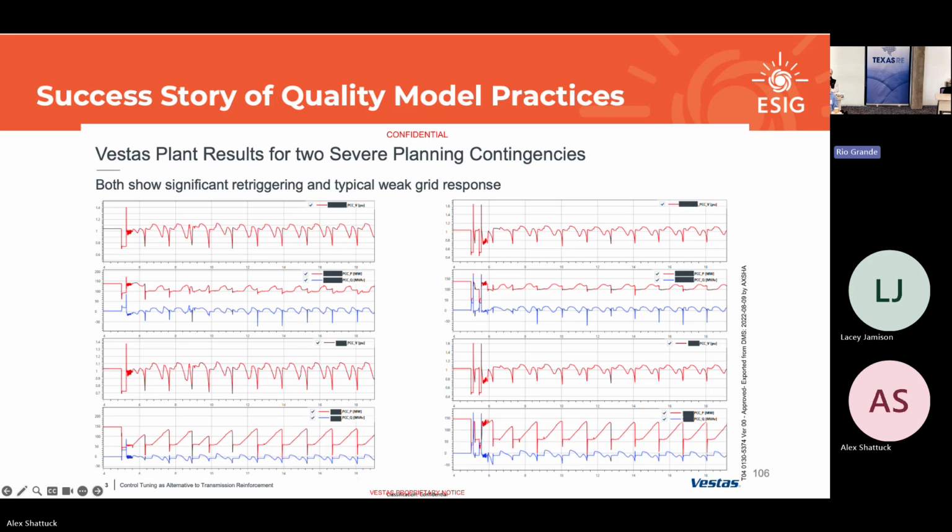In a weak grid, we're 20%. So same tuning as a strong grid, works perfectly in strong grids. In this 1.75, we're literally swinging up and out of the way. We're literally swinging in and out of voltage ride-through modes. So you hit under voltage ride-through at 0.9, you freak out and you're in ride-through mode and you crank the other way. And now you're up above 1.1, which is the other threshold, and you just cycle.